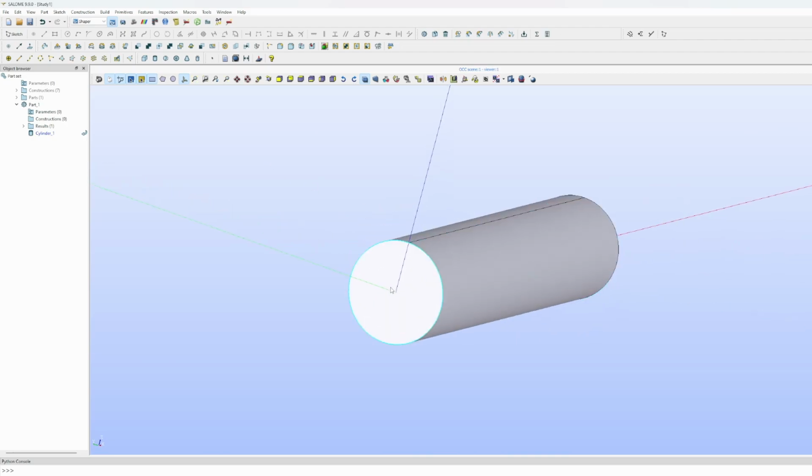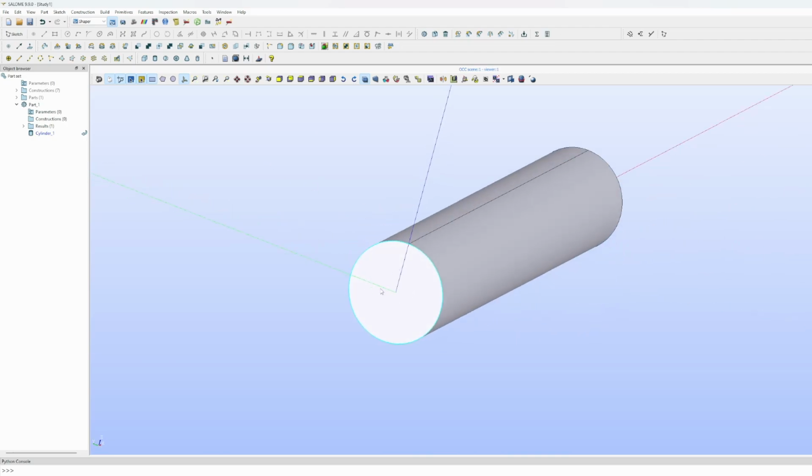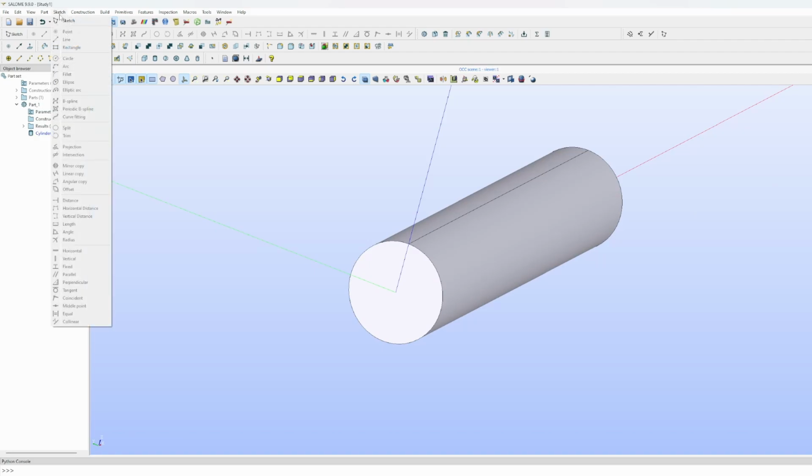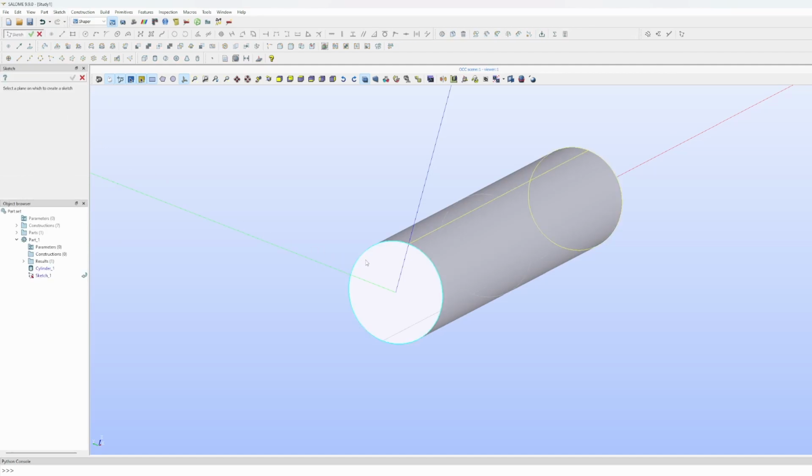Okay, so I will create this rectangular region on this face, and to create this I will create a sketch. So click the sketch, and we need to give a plane to draw our sketch. Here's how the Shaper module works: we create the sketch, and we can extrude or rotate or something to generate the 3D model. So I will choose this face as a base plane for our sketch.